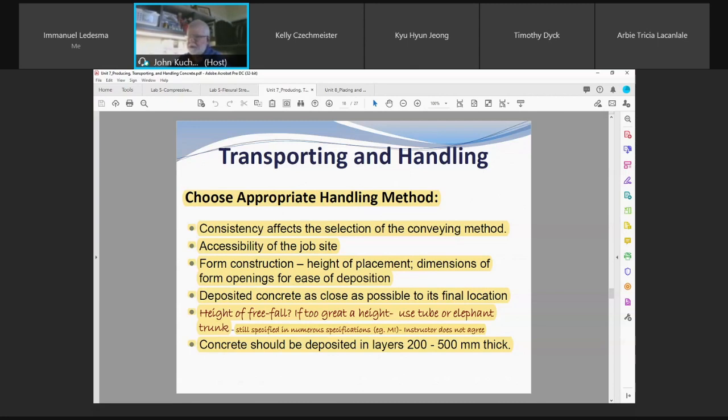But if you're dropping it straight down, and Subterranean did a study, and there's been studies all over, and even the ACI design manual has no restriction. You can drop that concrete 60 feet and it won't segregate. There's been studies where they've cored the center of the whole caisson 60, 70, 80 feet in depth. They pulled that concrete core out. There's no sign of segregation.